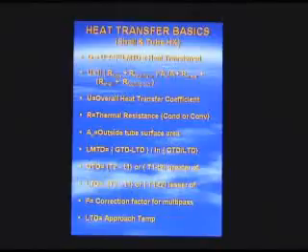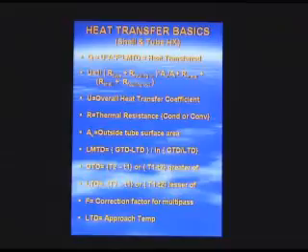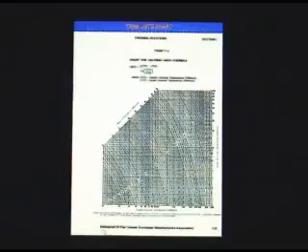So if you want to do better than that, it means you're going to need more surface area, just due to the ability to transfer the heat with that temperature driving force. We'll cover that in a little bit.